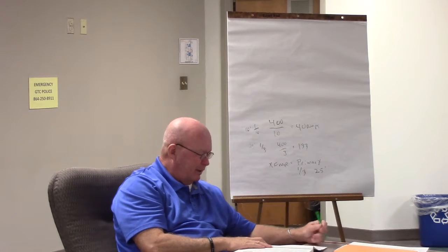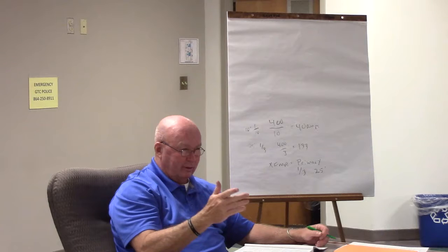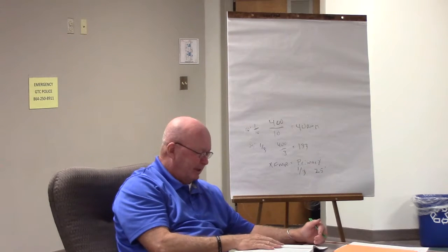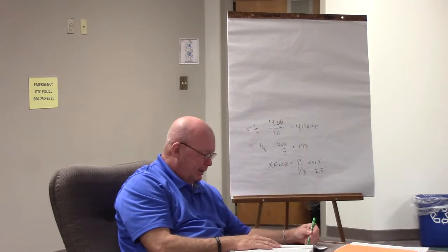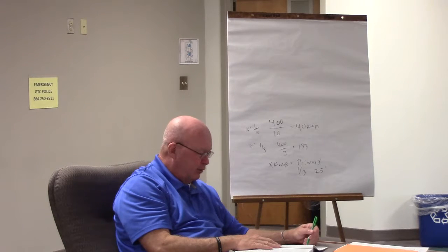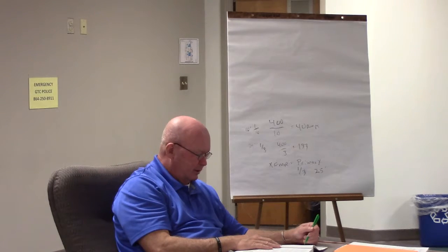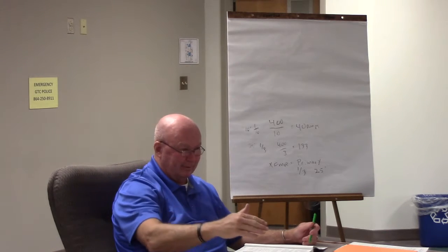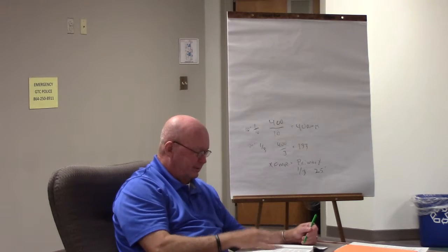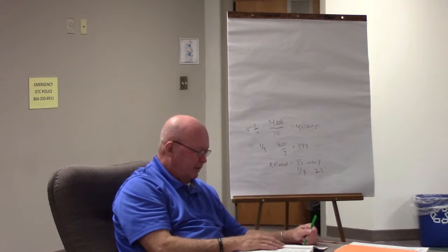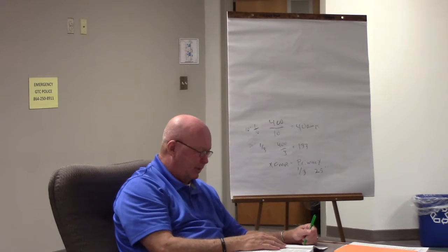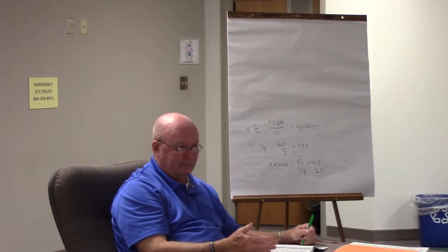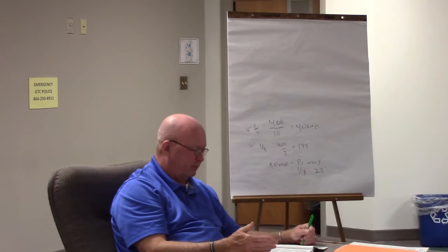Again, we see what? How much? 1/3. Let's just say that. Number 1 talks about 1/3. Okay. The ampacity of the feeder overcurrent protection device. Number 2 is no different than the other rules. It says it's got to terminate in what? Single breaker. Single breaker, set of fuses. Okay. Number 3, no different rules. Says it's got to be what? Protected. Yeah, protected.